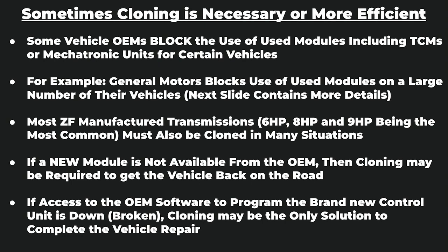Now, like I said, General Motors blocks the use of used control modules on a number of applications, and we will actually show you the link to the technical service bulletin that talks about that. So they're not making it any secret. They do want you to be aware of this. But again, remember, for some of these vehicles, the modules are no longer available from the manufacturer. So we would need to clone a used module in order to ensure the vehicle is still able to stay on the road.